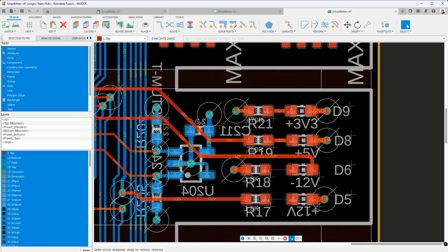Or you can also do isolations between groups, for example. But it's all possible because we have this in named group scope. So this is something that net classes couldn't do, that any of our other scopes couldn't do, but it's something that you can creatively leverage to granularly control your design. So keep that in mind. This is our example for component group. See you in the next one.